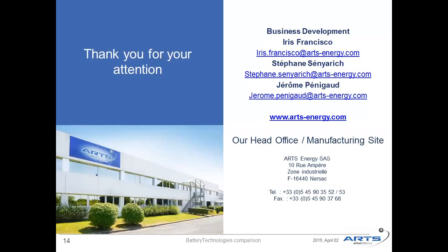We just had one last question during the webinar. Someone asking about storage state of charge: why use a state of charge lower than 50% for lithium ion products? As I said, it's just because if you store it at a high level of state of charge, you will decrease the capacity and you will have an irreversible loss. That means you won't have the full capacity of your battery after. This is only a question of performance.